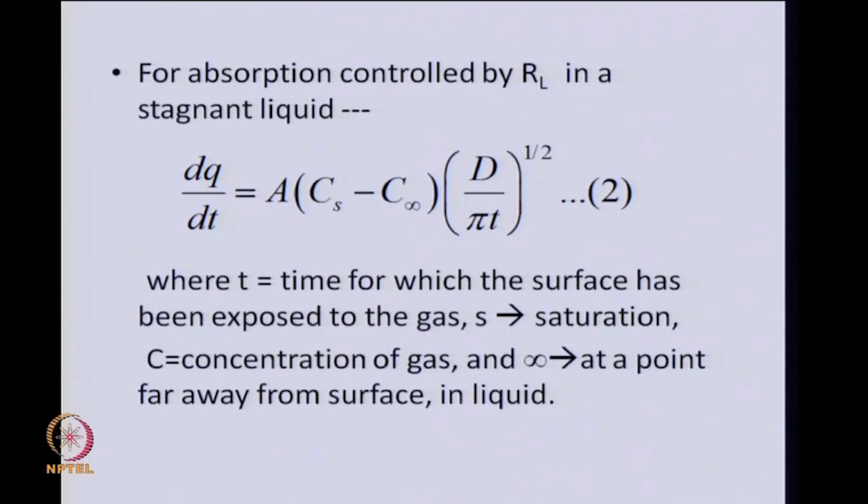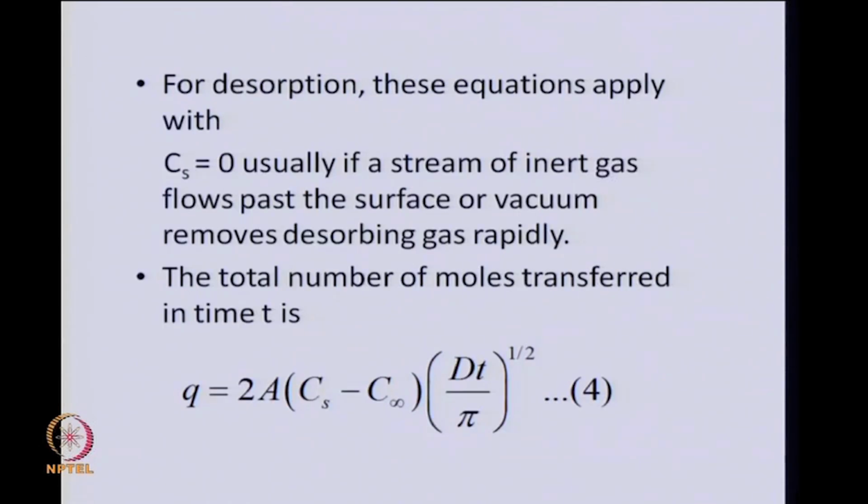the liquid, it is carried away and concentration of that solute in the gas phase drops to 0, or alternatively we could say that Cs is equal to 0 by actual application of vacuum. The moment a solute molecule is released, it just flashes off and vanishes. So, if we take Cs equal to 0, then we could use the same equation for desorption.